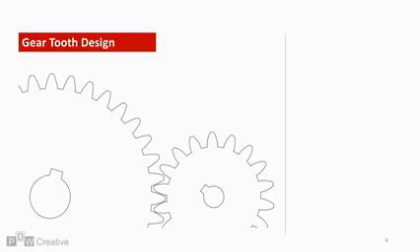The 2 gears shown on screen have vastly different diameters. If the smaller gear is the driver, for example, the size increase will cause a decrease in the revolutions per minute or RPM achieved by the larger gear. This is called gear ratio. We're not going to cover this in great detail, but it is useful to illustrate gears of different sizes, as no matter how big one is compared to the other, they must share certain characteristics in order to guarantee the two will mesh. So let's overlay some parameters.